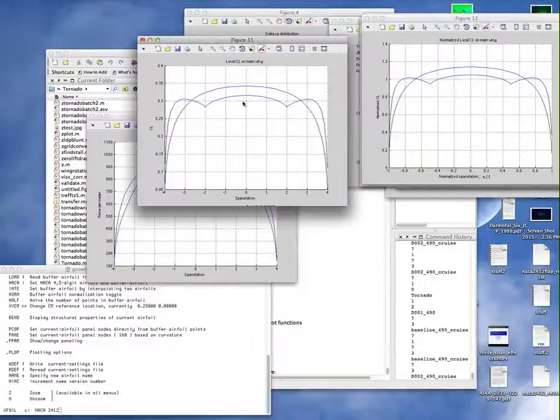Now, note that different sections are really running at different lift coefficients. We know from Xfoil that in a certain region at low levels of lift the drag is pretty constant, because it's really based on Reynolds number. You don't have a lot of profile effects. As you go to a higher angle of attack, the drag starts to rise, so you start having a CL-CD relationship. We're sort of on the edge of that, so there's some CL influence on our drag coefficient. But you can see that different sections of the wing are at different CLs.